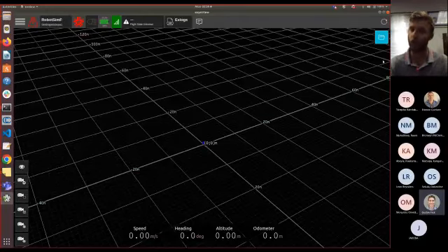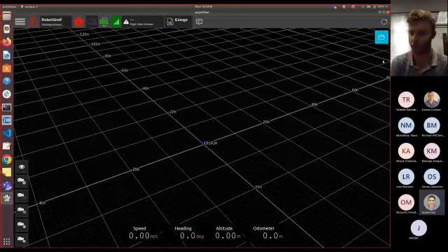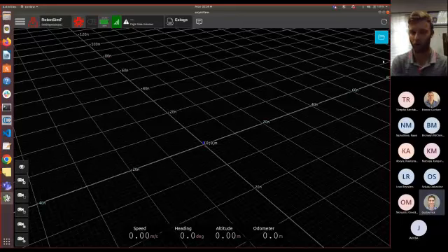As you saw, the volume I gave it was just a generic volume, but it came up with its entire flight path fully autonomously. That's fully based on the algorithm itself, the SLAM algorithm. It's able to identify surfaces, determine a certain factor of safety, and make sure it doesn't fly too close to any obstacles that are in the way. So yeah, it won't fly into a wall.